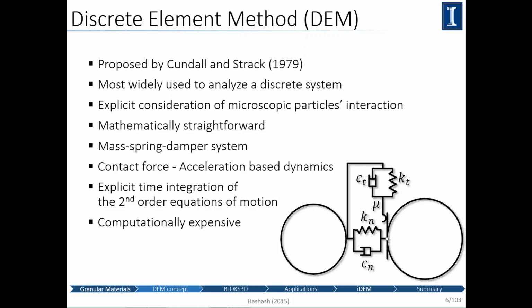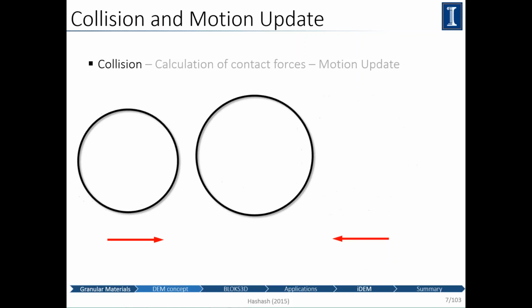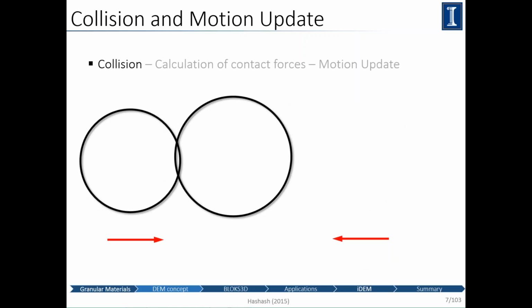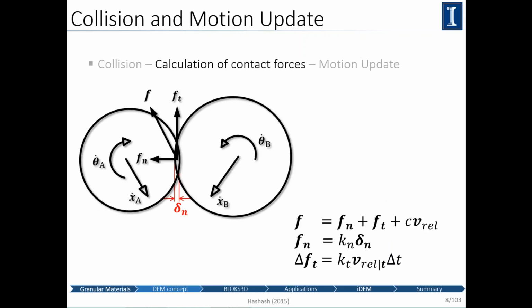Visually, we can see it, but you need to do that mathematically when you're doing a simulation. So this is the type of simulation you do: you have a collision, and based on the collision and the spring forces, you can estimate particle forces. And one of the issues you have to deal with when you are dealing with spherical particles is spin.